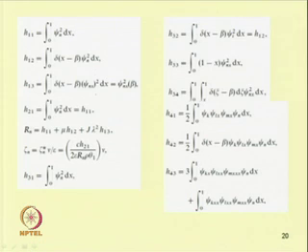So, these are the expressions for the integrals we have used in this equation. One can see there are many integral terms one has to evaluate for finding the coefficients of the system, where psi_n is the shape function of the system, and in this case the shape function is taken as that of a cantilever beam with tip mass.